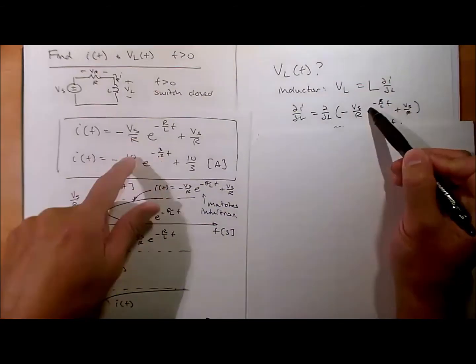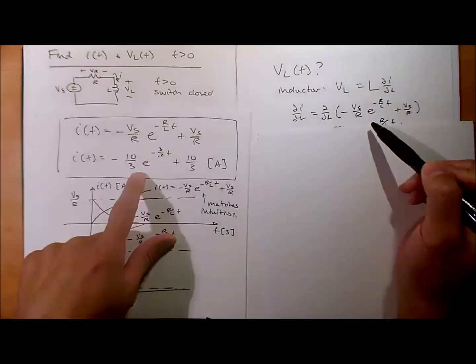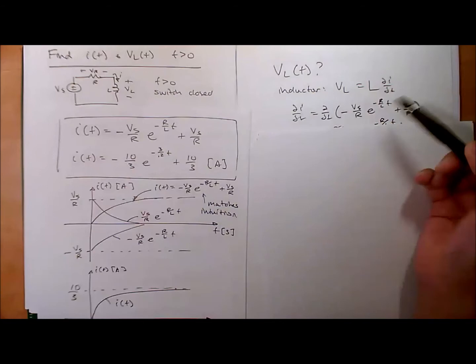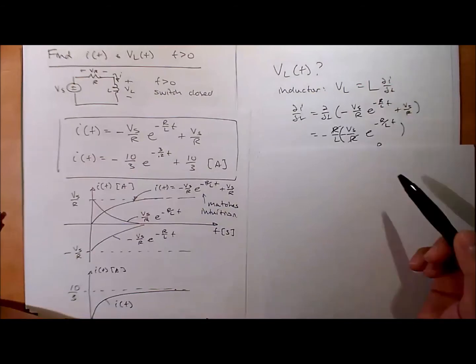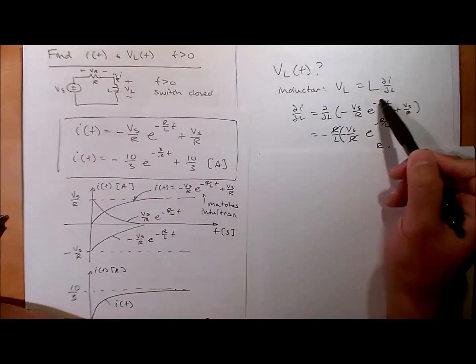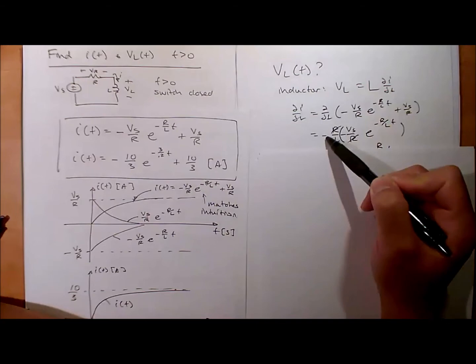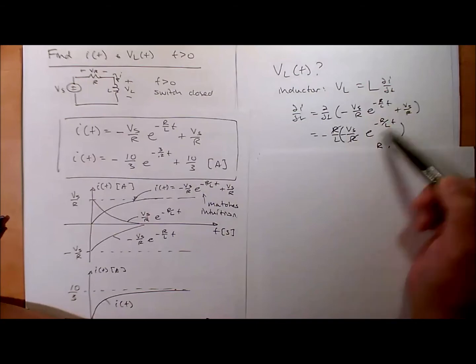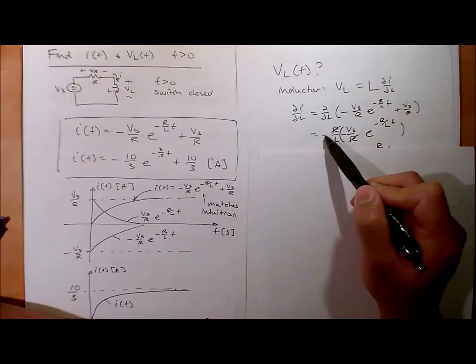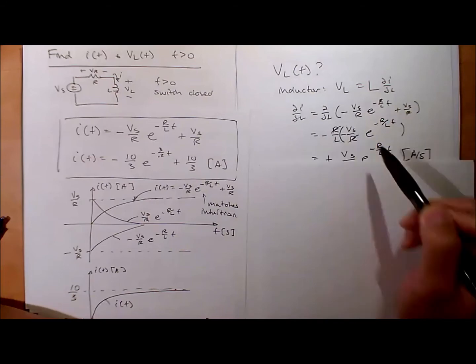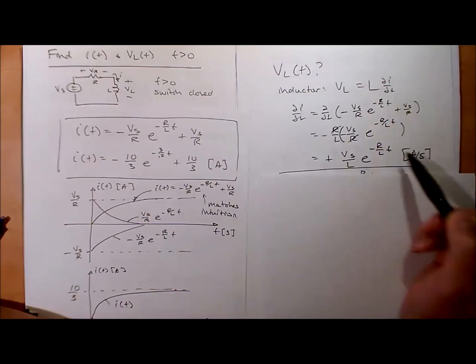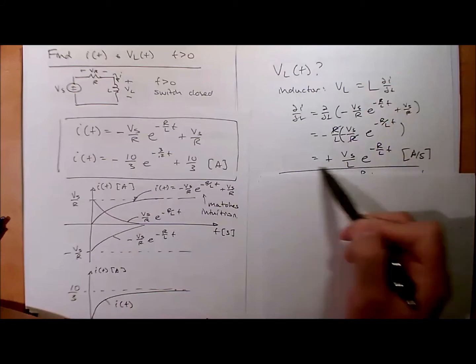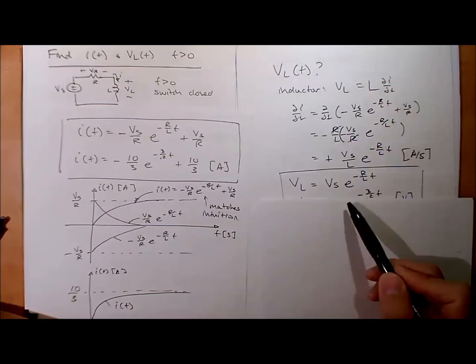The derivative of this is the derivative of that, right? They're the same thing. This is just the symbolic result. This is the numerical. Let's do symbolic first, and then we'll punch in the numbers. That way we can see where everything's coming from. The derivative of this, okay, let's be very careful. It's minus R over L comes to the front. That's it. And then this goes away. Oh, that was easy. Okay, minus minus becomes a positive. R's cancel. So you get Vs over L, e to the minus R over L t. That is your derivative equation, right?